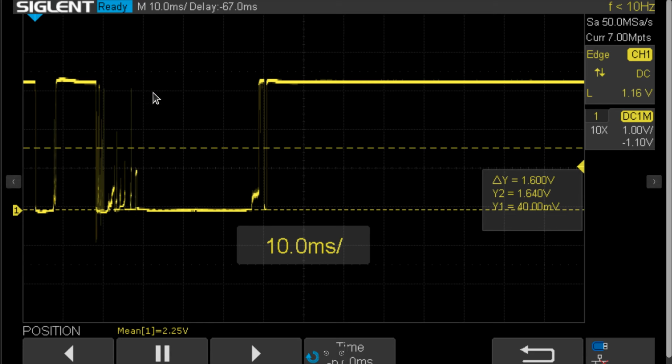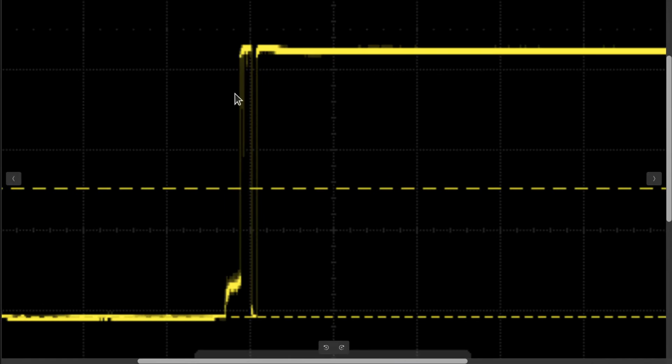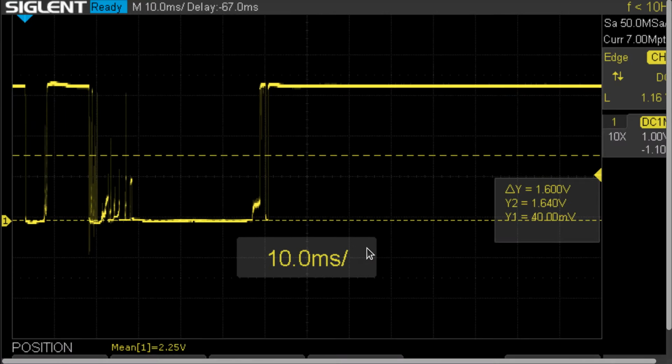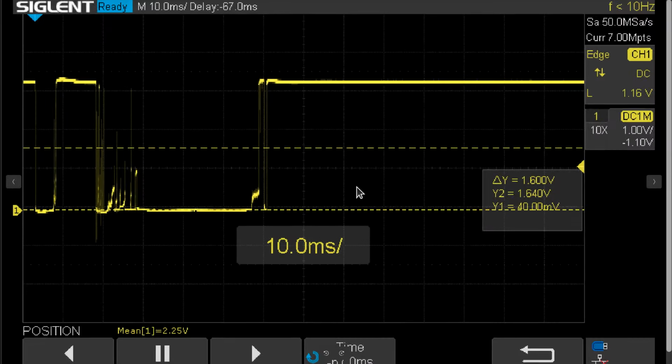It says you can change, but you need to stay there for a little while before I will consider the fact that you really have changed. And if you think about it, if the signal does this and it goes 1, 0, 1, 0, 1, 0, and it's bouncing back and forth, could do this for an hour and a half. And you're not going to know anything on the output signal of this module because of the way this particular debounce circuit is implemented, all right?